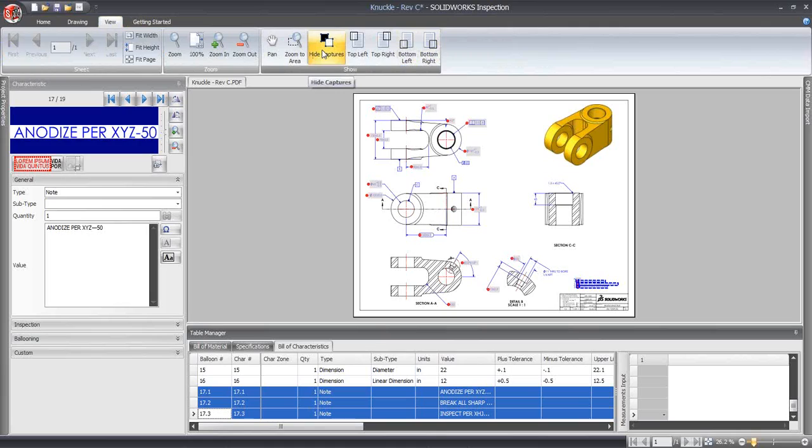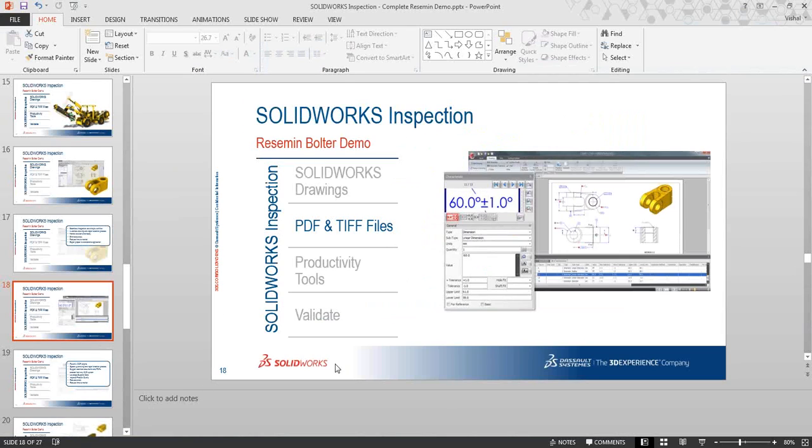Here we'll see, like you can see, if you think that something is missing, you can just hide and show whatever is captured. You can see it will show me, and it will show if anything is missing. So you can see a couple of dimensions you have missed from there. So this hide capture is again a good thing. You'll come to know what you have missed to capture. Okay, so this was great, let's jump back to our presentation.